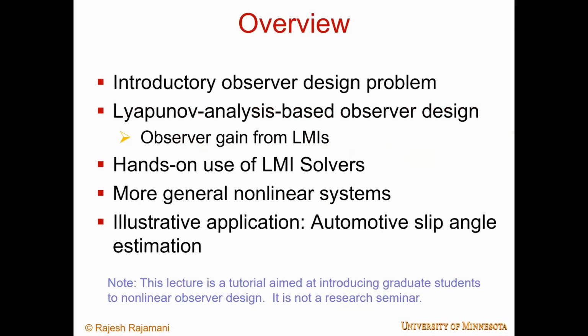So I'll start the tutorial by using a simple nonlinear plant for introducing the observer design problem. Then we look at Lyapunov analysis-based observer design and see how to set up the stability condition in the form of LMIs for designing the observer gain. Then we look at use of LMI solvers in MATLAB to solve the LMIs and find the observer gain.